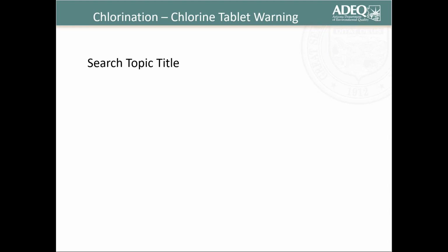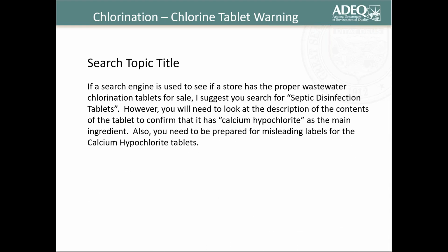Now, search topic title. I wanted to throw this one in here. I found it very humorous what type of titles these home improvement and hardware stores give to the calcium hypochlorite tablets. So if a search engine is used to see if a store has the proper wastewater chlorination tablets for sale, I suggest you search for septic disinfection tablets. However, you'll need to look at the description of the contents of the tablet to confirm that it has calcium hypochlorite as the main ingredient.